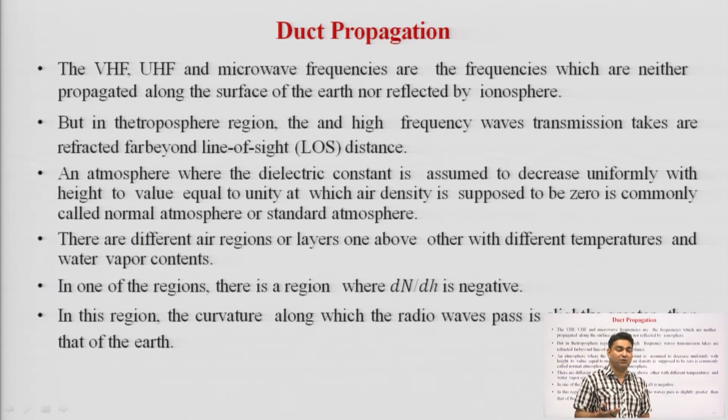Then what about the frequencies above 300 megahertz? We have to adopt some of the modes of propagation which utilize these frequencies for communication purposes, and the distance between the transmitting antenna and receiving antenna must be very much larger than the conventional modes of propagation, which are limited up to line of sight distance, or the multiple reflections by skywave propagation, whose distances are limited by the ground losses.